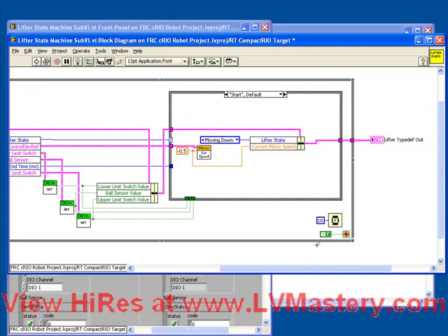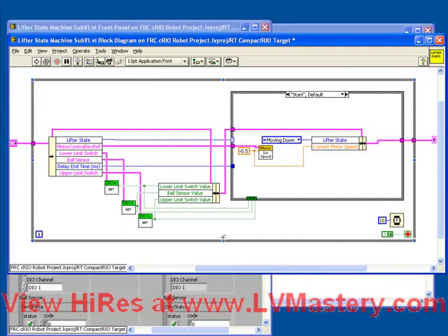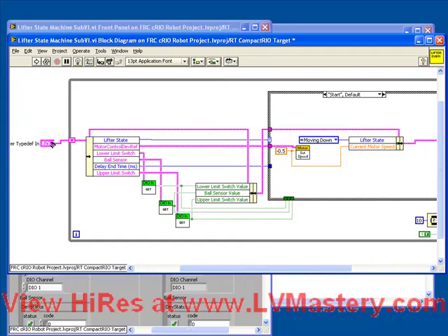Depending on the importance of your VI, you can choose that to be 10, you can choose that to be 1, or you could choose that to be 100. Of course, anything in between. We're almost there in terms of what we need to do to make this VI work, but there's one critical element missing. Remember that this state needs to be remembered from loop to loop to loop. So it's extremely important that we make sure that we have a shift register into which the value of our cluster gets passed over and over and over again.